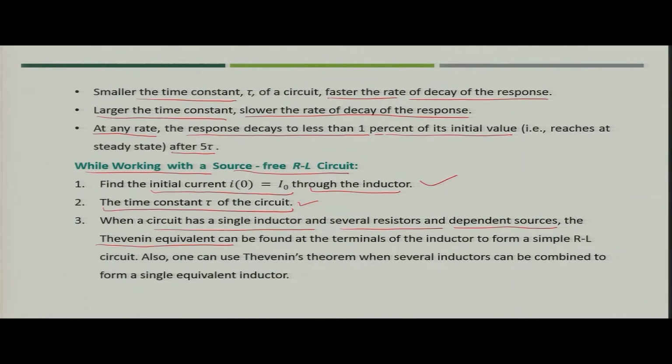So, we will use Thevenin equivalent at the terminals of the inductor to form a simple RL circuit, or we can use Thevenin's theorem when several inductors can be combined to form a single equivalent inductor. So, in summary, if we have a circuit with multiple inductors and resistors, we can utilize Thevenin's theorem to simplify the circuit and find the response of the circuit.